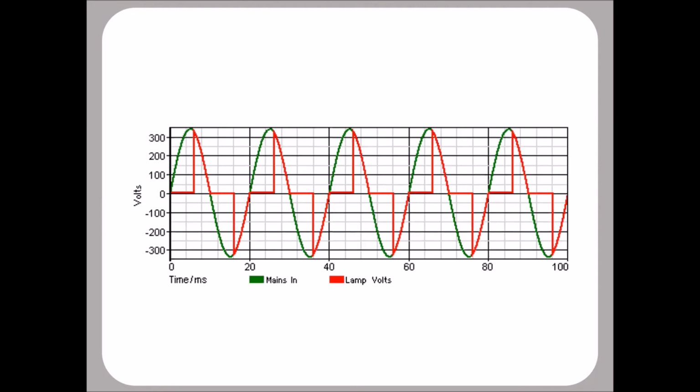You can cut out parts of it depending where you set the gate pulses with your little twiddle knob. So your lamp gets the red waveform. We're back to lamps now, which are perfectly happy with AC. It's not rectifying, it's just throttling some of each half cycle. So the lamp intensity clearly goes down when we use a triac.